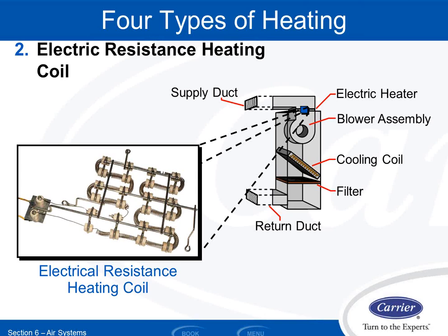So electric heat, in all cases, is always, always, always more efficient than the best gas furnace or gas boiler that you can buy. But that doesn't mean it's less expensive to run. It just means it's more efficient. Whether it's less expensive or not depends on your utility costs. So if you're here where I'm sitting right now in the Nicor gas territory, Nicor gas is fairly inexpensive. So the gas furnace and gas boiler typically always beat the electric resistance heating in terms of energy cost, but electric resistance heating is actually more efficient.